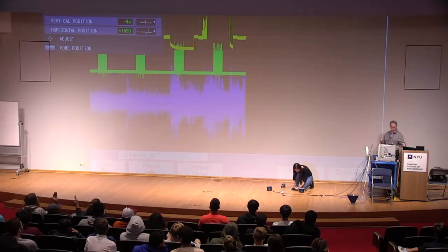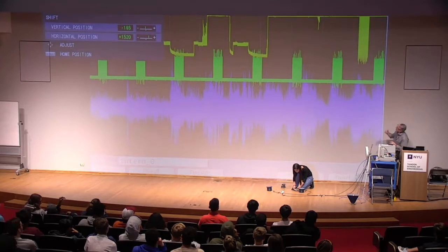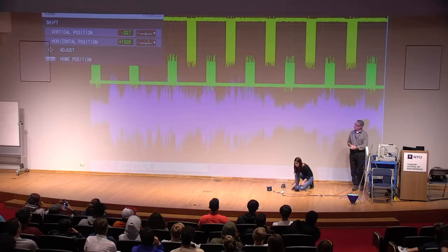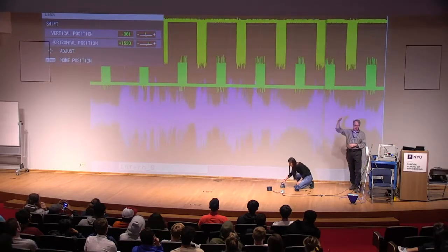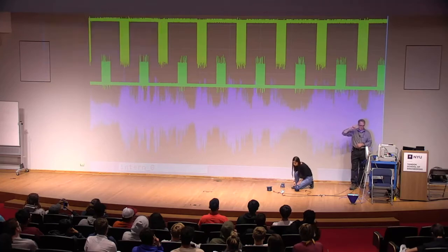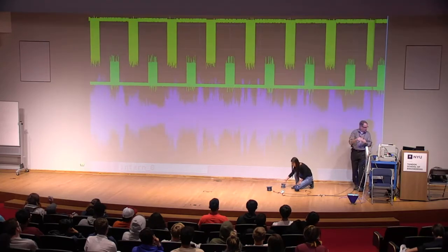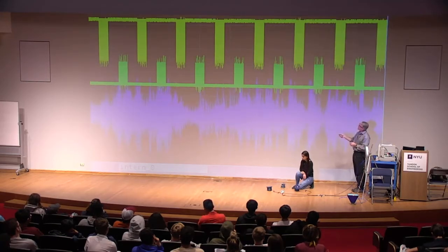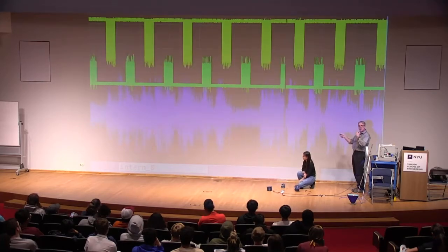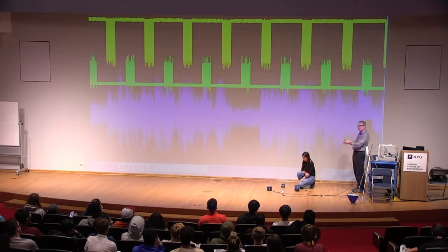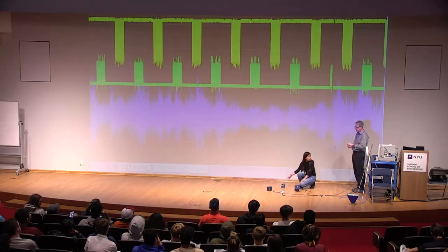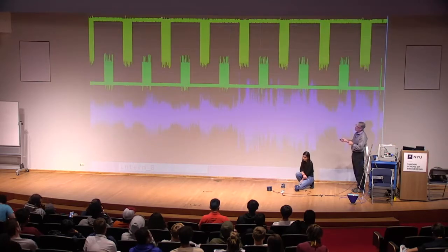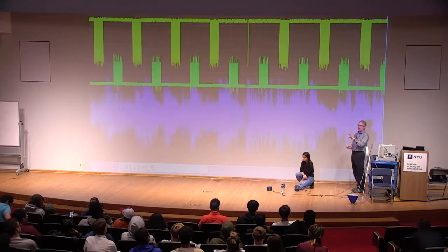All right, so the 3 waveforms you're looking at, this is time. Time is marching on. The yellow waveform is all on one channel. What we're seeing is amplitude changes. When that beacon is on, you're seeing this burst of signal. In other words, this is the first 5 kilohertz beacon. Its energy is here, and then it shuts off. So you hear it on, you hear it off. If I stay quiet for a second, you can hear these 2 beacons going back and forth. The green one, the lower one, is the other beacon. That's the burst of sound at 8 kilohertz.